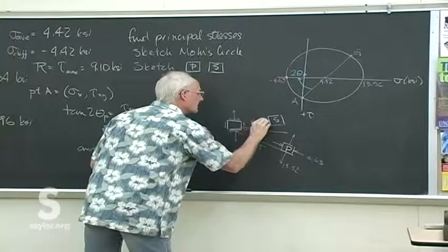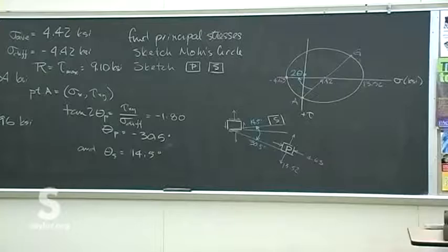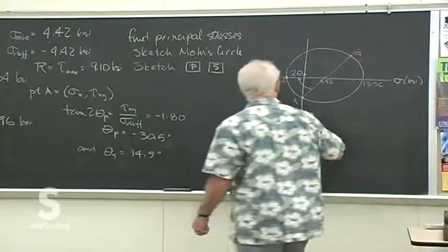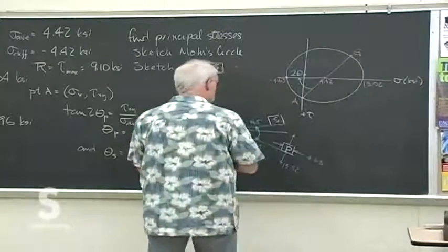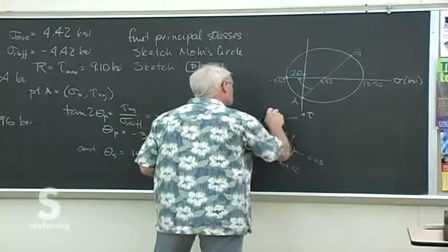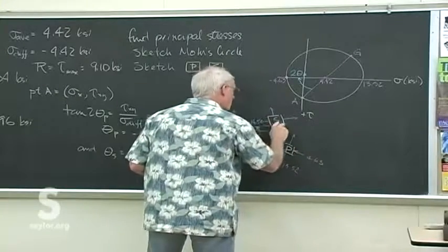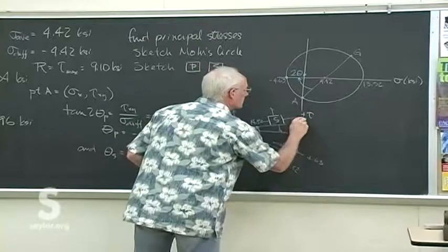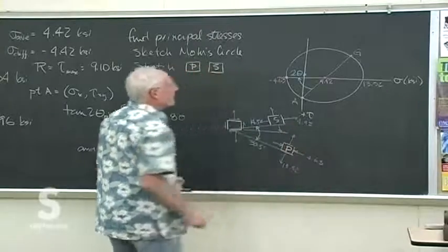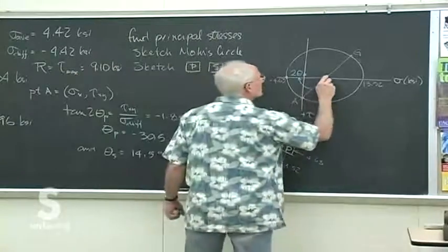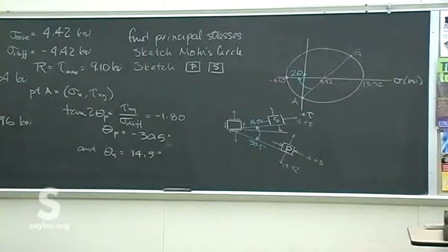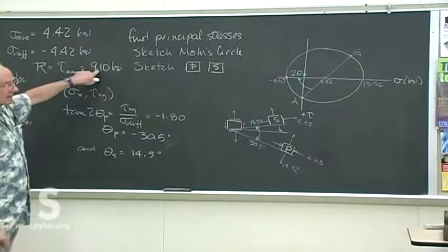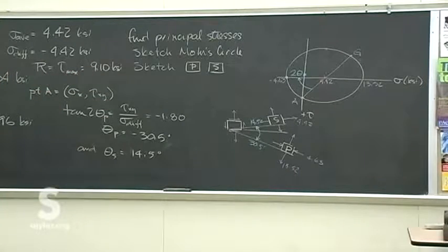And we know there we have the average normal stress on each face, which is a positive 4.42. So we sketch that in. And at that point also we have the maximum shear stress, which is 9.1. And so we can sketch all those in there.